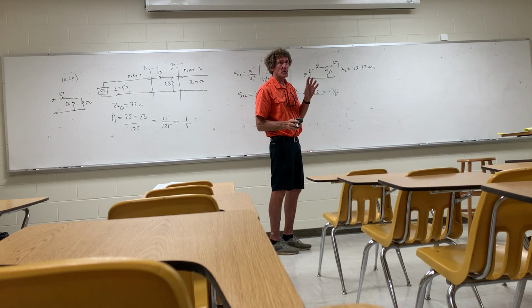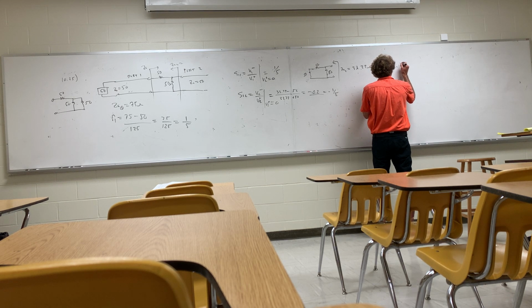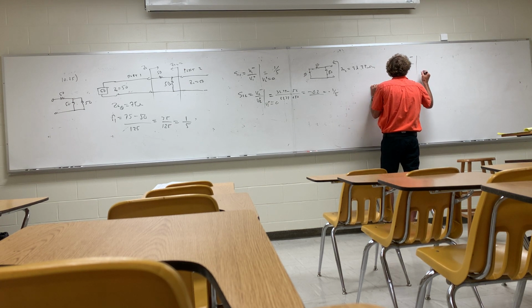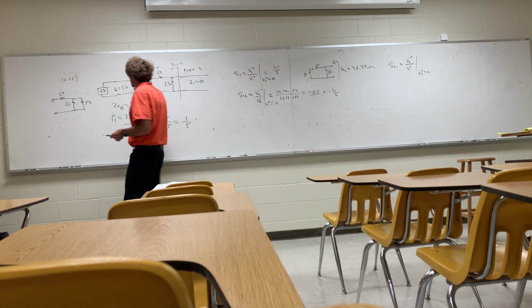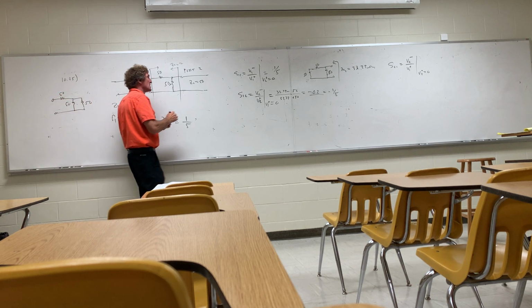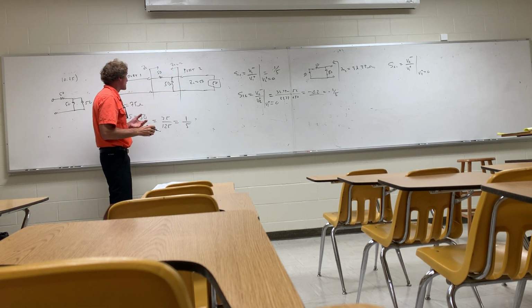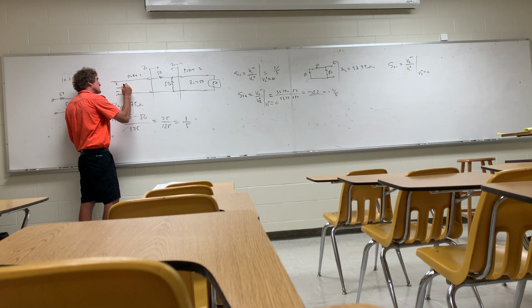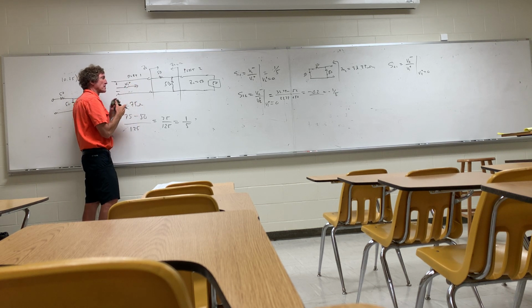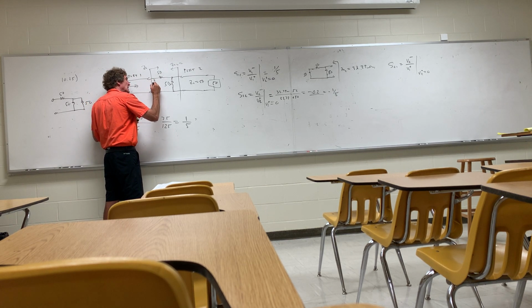Now we need the forward voltage gain. Now I want to get S21. That's equal to V2 minus over V1 plus, assuming V2 plus is 0, right? So now, mentally, we're going to do this. You don't have to do this, I'm doing it for your sakes. Now I'm going to put 50 on load here, so you know this thing's matched. So if I put a voltage waveform here, I'm going to have this V1 plus coming in. Now remember what happens here. The key is getting this voltage right here. I need that V prime.